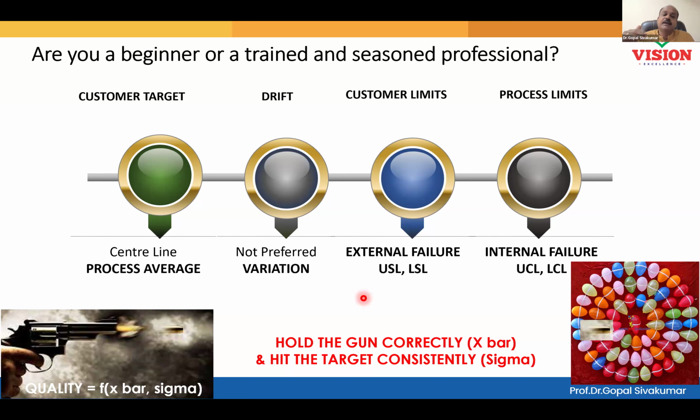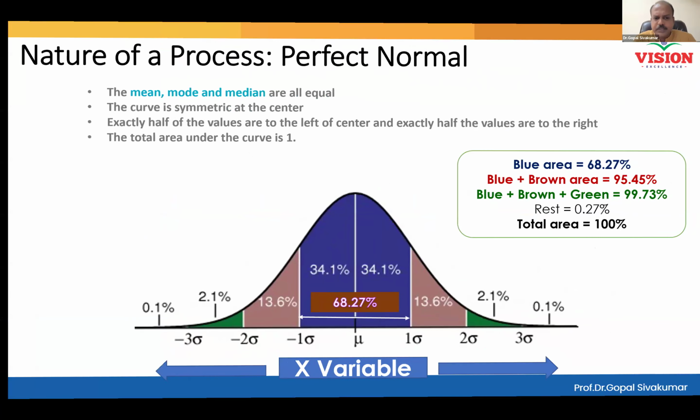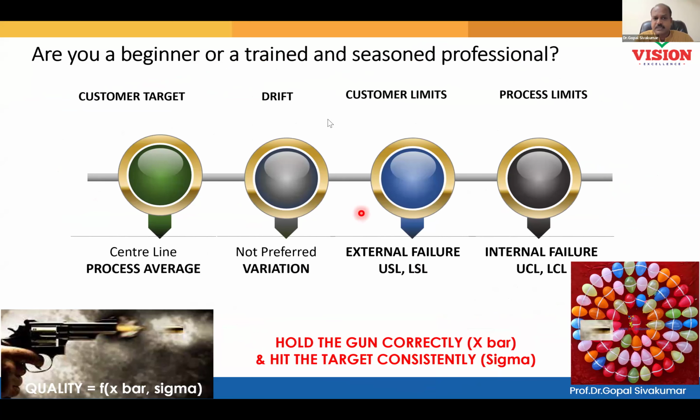Will you understand, am I saying that Cp equal to 2 and Cpk is 0.75? Oh, that's possible. That's possible. Cp is 2 and Cpk is 0.7, isn't it? Yes. So how to interpret this? Sir, now I understood his question. Cp equal to 2 and Cpk is 0.7 means your process is shifted.